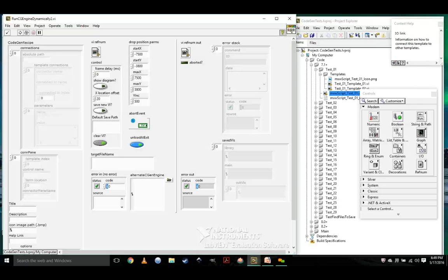That is correct. Does that need to be specified on both templates? No, just one. So you can leave that blank if it's already specified in the other. No, the original Codegen engine required matching types, but it doesn't anymore. It doesn't matter. In fact, you can connect terminals of any type to themselves, and as long as it cleans up correctly, you're good. Because basically at the end, it's going to go in and remove all the excess terminals, and if that results in a good wire, you're good. If it results in a bad wire, it will be removed, because that's one of the cleanup steps: bad wires are removed.